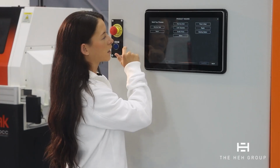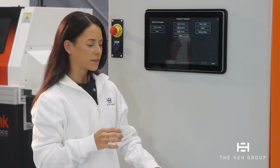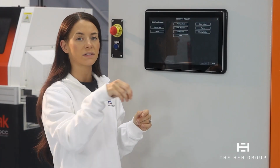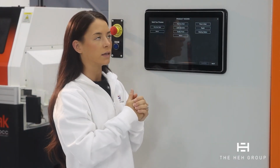So what is the datum? This is a really important feature. When you look at the Agile system, there's this little tray that sticks out, and some people don't need it. However, if you do need a really accurate regrip, depending on the types of parts that you have, you're going to want to pick that part from the nest, put it on the datum, let it regrip so it's super accurate, and then load it into the machine.